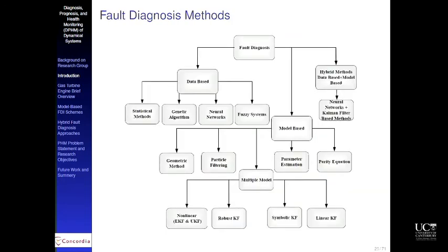There are many methods in the diagnostics. As far as the model-based approaches, you have nonlinear filtering methods based on Bayesian methods. You have parameter estimation-based methods, and then you have state and parameter estimation-based methods using Kalman filters: unscented, extended Kalman filter, cubature Kalman filter. You have all these ranges of filtering methods that people have developed depending on the complexity of the problem that we can use for model-based approaches. For data or machine learning-based, you have, of course, neural network, fuzzy, genetic, and these methods are also used.